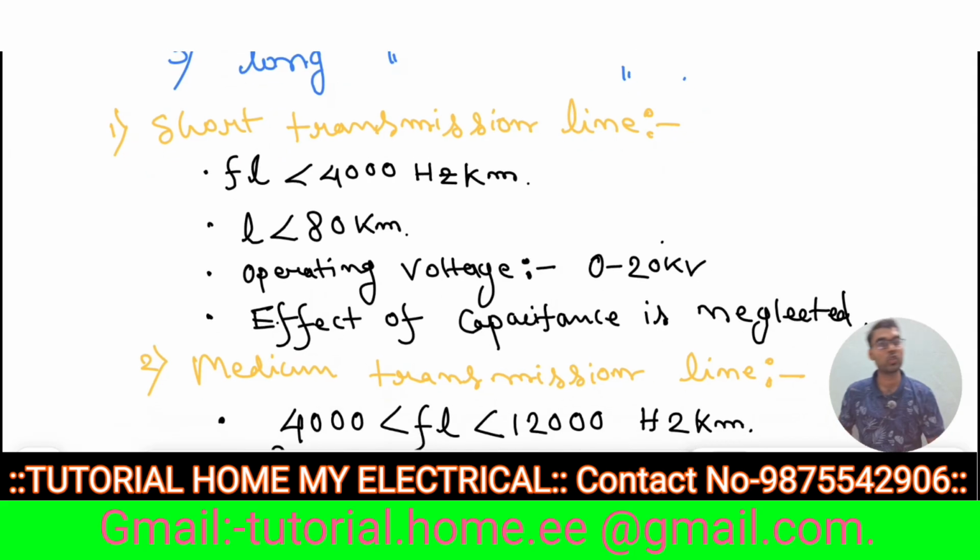For a short transmission line, the multiplication of frequency and the length of the transmission line is less than 4000 Hertz kilometer. The length of a short transmission line is always less than 80 km, and the operating voltage is between 0 and 20 kilovolt. For a short transmission line, the effect of capacitance is neglected.